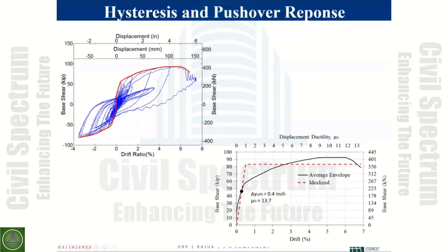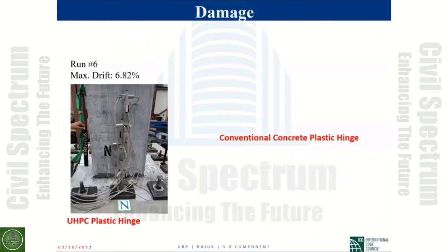That indicates that as the loading was reversed, and at the end of the earthquake, the displacement forces circled around here, meaning that there was no permanent displacement, or essentially permanent displacement was removed. Using the conventional method of estimating ductility, this column gave us more than 10% displacement ductility, which is way more than what we normally expect from conventional construction.